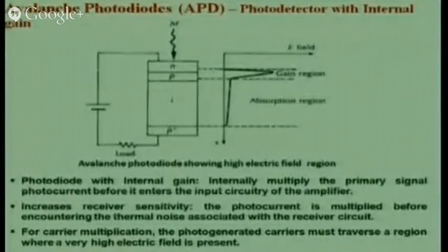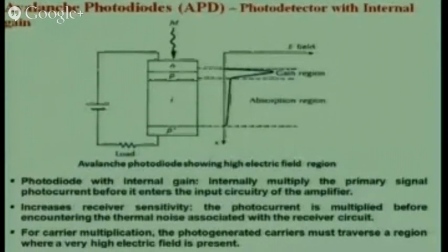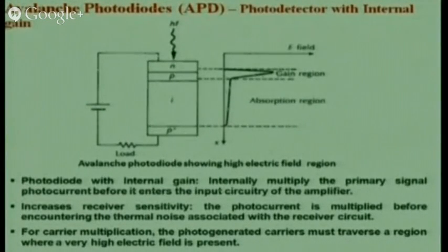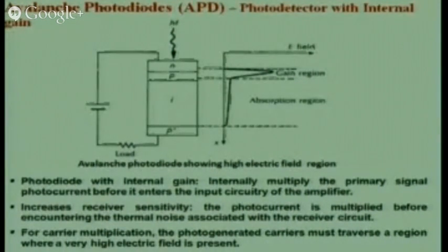That situation comes when you have an avalanche multiplication within the setup itself. Suppose you have a PN junction. Now I apply a much larger reverse bias, so that the electrons produced because of photocurrents gain enough momentum while moving to the respective junctions. They attain enough kinetic energy to bombard the silicon lattice of the p or n sites. So when they have enough kinetic energy, they can liberate further electrons. One electron liberates further electrons, which leads to an amplification within the photodiode.